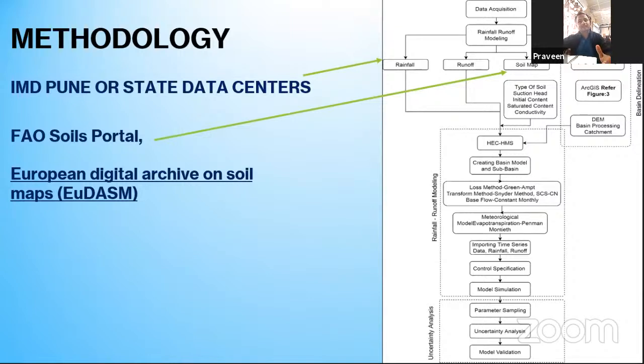So it should make sense. Even nowadays, techniques are developed where we can match data. Suppose there is a certain rainfall and you have relatively very poor quality runoff data, we can match those data using calibration and validation techniques. Such advanced techniques also came up. The thing is, you must understand what's happening inside, and then you should have quality data to understand the complete response of the catchment for the given rainfall. This is the definition of the hydrograph, right?